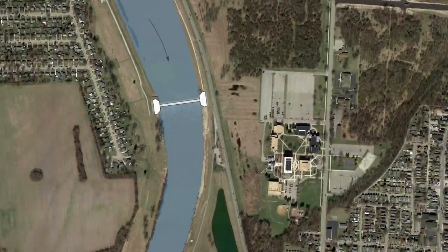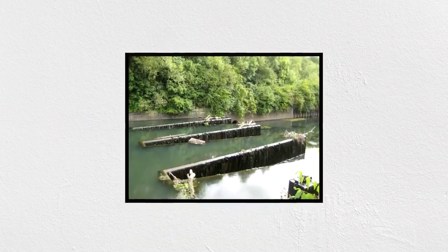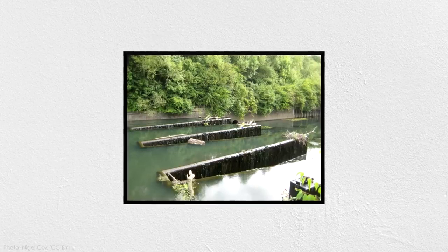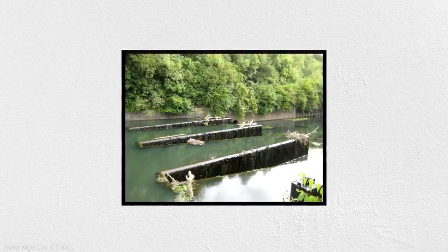So what if we could get the benefit of a controlled outlet without the disadvantages of increased complexity and operational obligation? Well, there's one more trick that hydraulic engineers have up their sleeves. Remember when before I said you could only fit a certain length of weir within a fixed footprint? That's not completely true. We can actually fold a weir to get more length within a given space. This is called a non-linear weir, and it's used in situations where you want greater discharge within a given footprint, but without the need for actively controlled outlets.